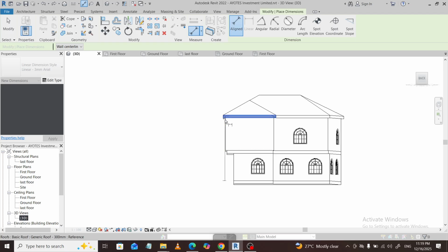Revit instantly displays the result as a temporary dimension on screen near your cursor. This is a straight line distance between the two references in 3D. If needed, adjust your view or zoom in so you can confirm you've snapped to the correct features before you click. When you need the length along an element rather than a straight line distance, switch to Measure Along Element.